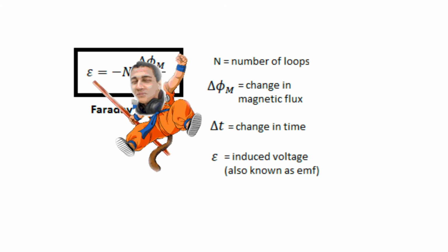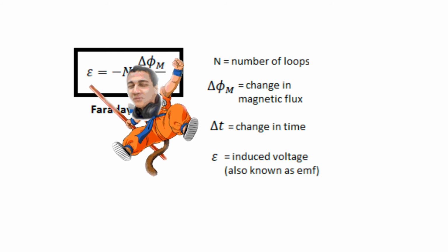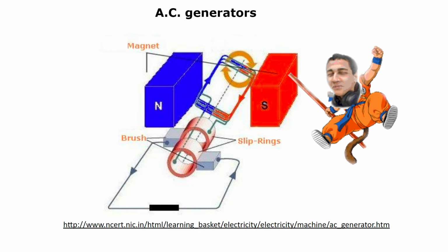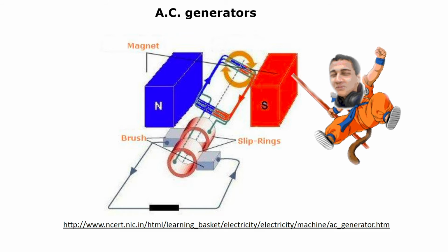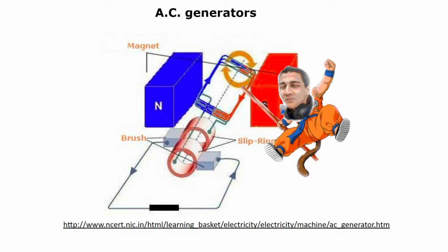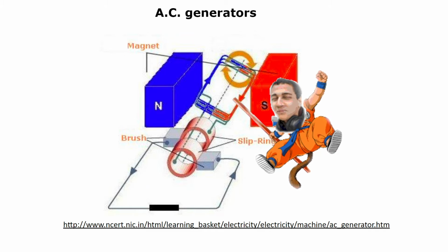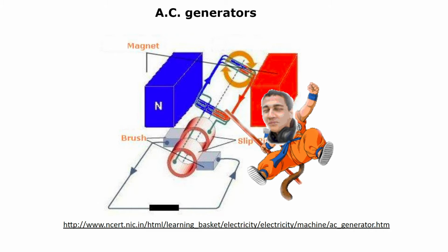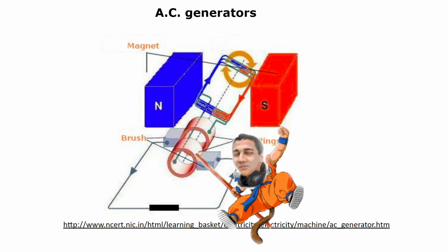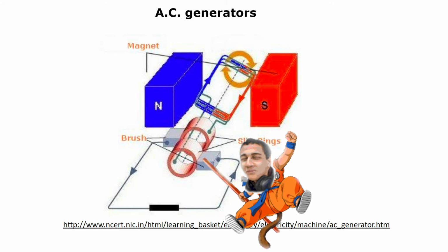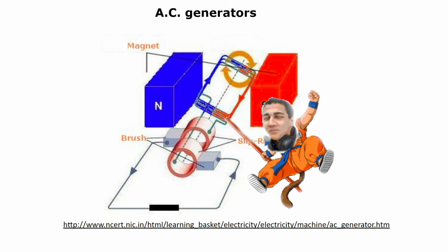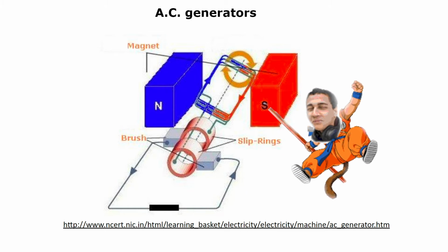One very important application of electromagnetic induction is the AC generator, or alternating current generator, the method that is used universally to produce electricity. A coil is made to rotate in a region of magnetic field. This can be accomplished in a variety of ways, such as a diesel engine burning oil, falling water in a hydroelectric power station, or wind power. The ends of the coil are firmly attached to two slip rings that rotate along with the coil. The slip rings touch carbon brushes that transfer the current to an external circuit. The function of the slip rings is to maintain constant contact with the same side of the coil.